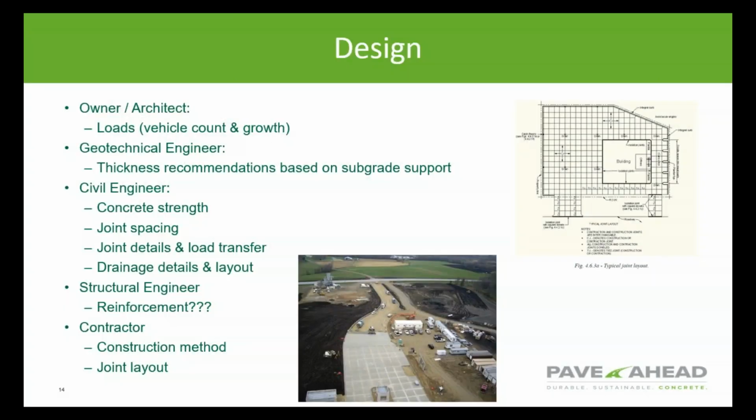Depending on your background, your opinion of who is responsible for pavement design will differ from others. So let's explore some interested parties and see how they influence the design. The owner should supply the type of loads as well as the frequencies of these loads. If it's anticipating that there's going to be additional vehicles over time, then a growth rate would need to be provided.